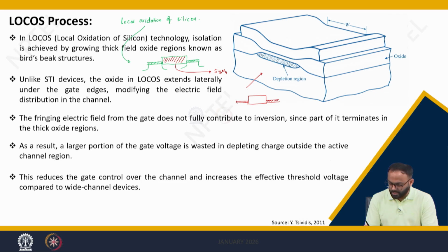of the other transistor. However, when you go for oxidation, meaning oxidation either using O2 or H2O, this oxidation is not exactly vertical. It means it penetrates somewhere into these isolation layers, and hence you will get this kind of structure, correct.